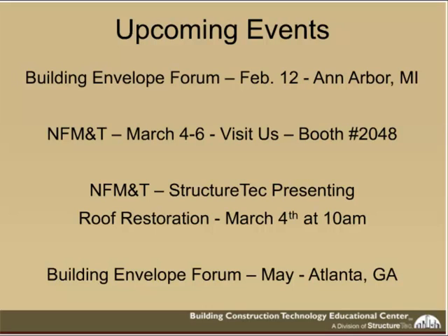Okay. Thanks, Russ. Good question. We've got Jim from the Chicago area. Jim's asking, do all weathering grade bricks absorb moisture? All bricks absorb moisture. Weathering grade bricks absorb less moisture and are less susceptible to deterioration. So in the northern climate, your severe weathering grade brick is still going to absorb moisture, but they are more moisture resistant than the ones that would be used in the south. That's correct.